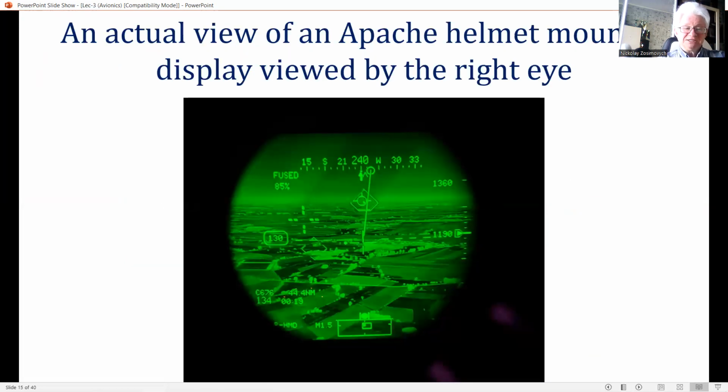The display source on a simple helmet-mounted sight typically comprises an LED matrix array. This can range from a simple fixed format addressable array to, say, a 32 by 32 matrix array, which can display some limited variable symbology, including alphanumeric. The display image is relayed to the visor by means of a compact optical prism and reflected from the visor into the pilot's eye. The surface of the prism has cylindrical and spherical curvature to correct optical error.